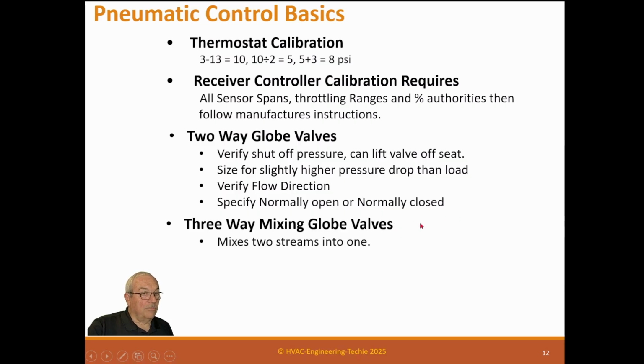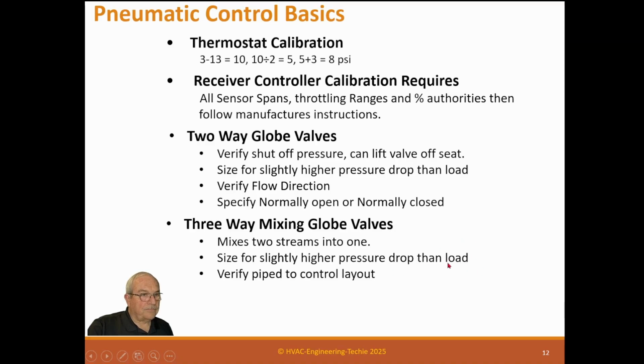Three-way mixing globe valves. Mixes two streams into one. Size for slightly higher pressure drop than the load. Verify the pipe-to-control layout, because you can pipe these two different ways. So that's important. Verify normally open or normally closed, stem up or stem down.